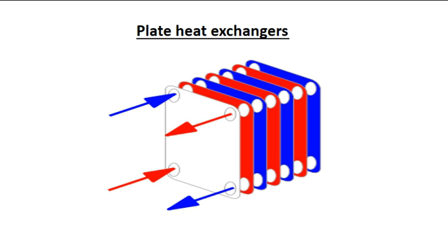The plate fin type of heat exchanger uses sandwich passages containing fins to increase the effectiveness of the unit. The designs include cross-flow and counterflow coupled with various fin configurations such as straight fins, offset fins and wavy fins.